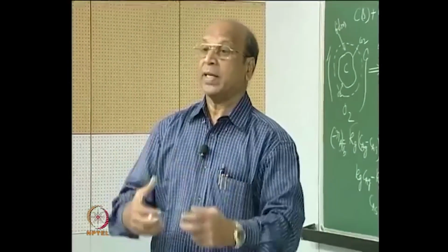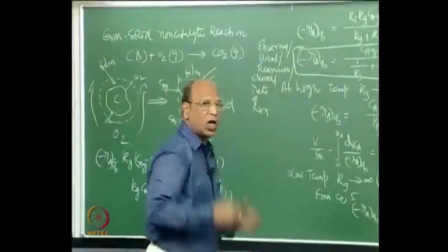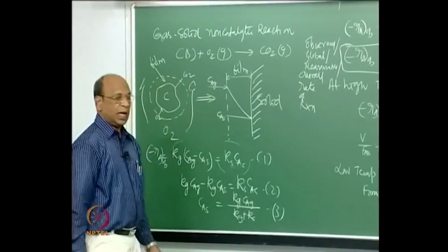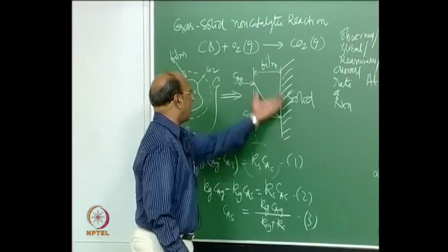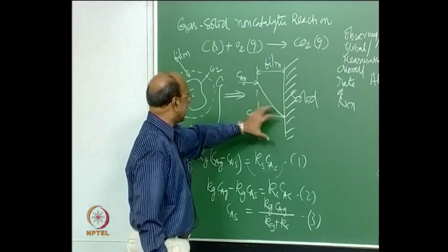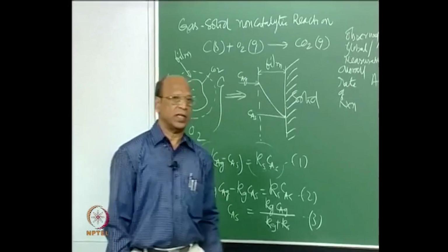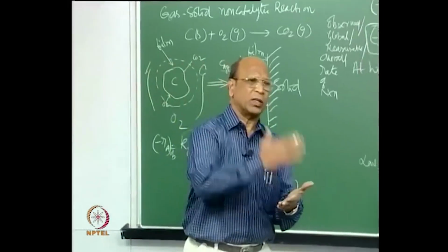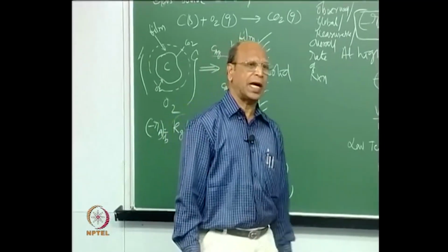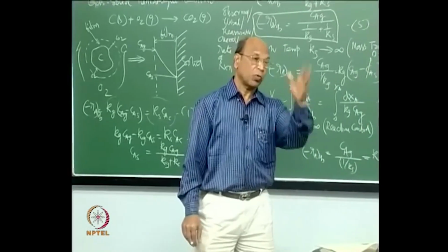Out of that, what are my important steps and how do I show them as pictures? All this is imagination what I have done, and now this is the picture, and this picture leads me just to draw the profile graph, right. These are the profiles, like that I may have some 3-4 steps, and everywhere I have to draw the profiles and list out what is step 1, step 2, step 3, step 4, and you will see here most of the time reaction is only 1 step and mass transfer steps can be 4 or 5.